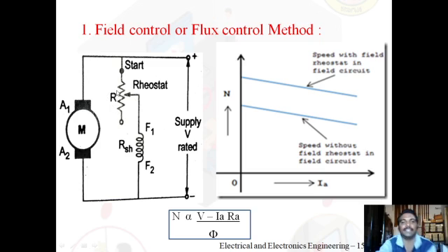Initially, let us start the analysis with R equal to 0, that means the pointer at start position. When the voltage is applied, the current starts flowing through the armature and also through the shunt field winding, which produces a flux. Therefore, according to the working principle, the motor starts rotating and torque is produced. So what about the speed of the motor?